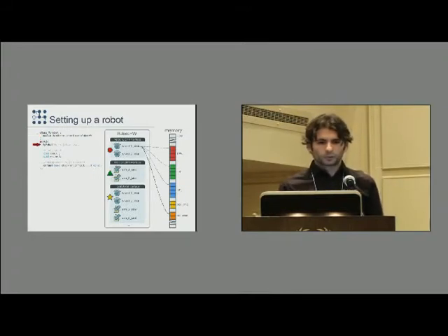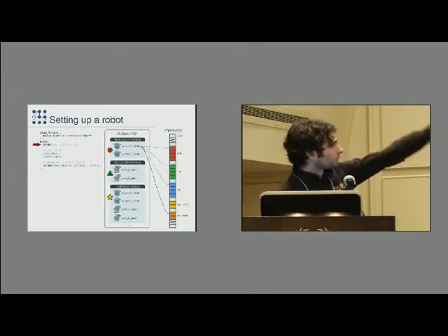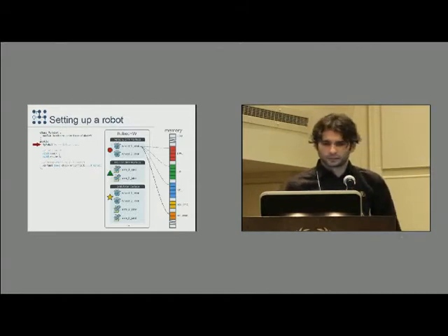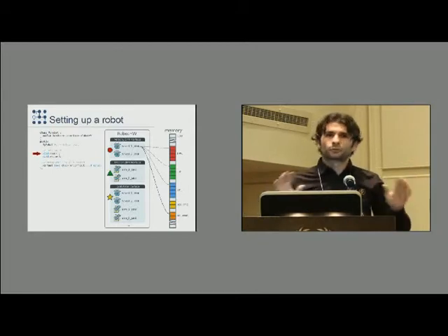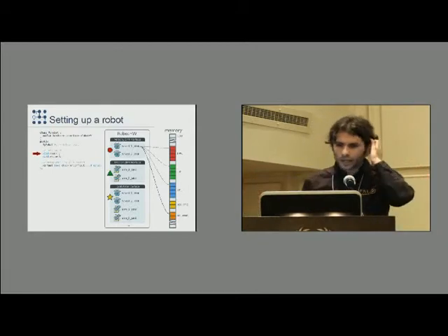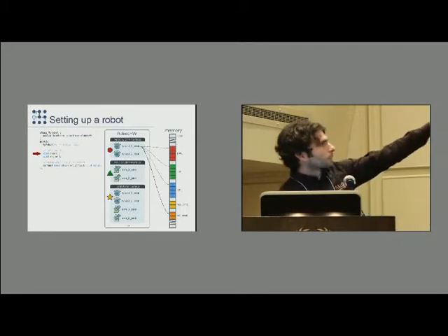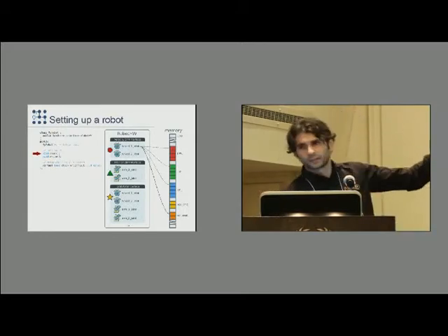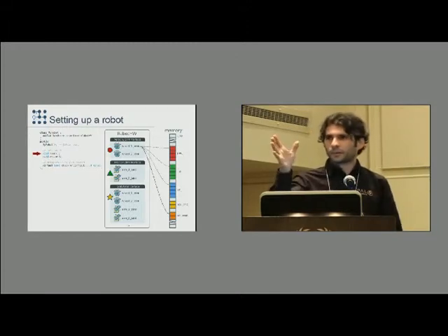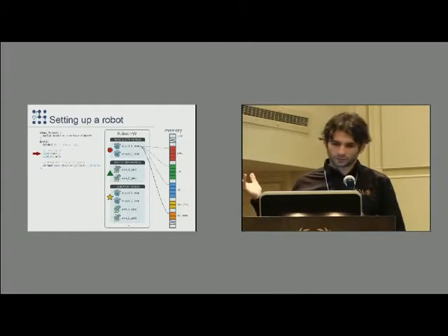In the constructor, you would set up your robot, which is basically filling up what you see in the drawing. And then there's a couple of methods where you read and write, and this is up to you. This is where ROS Control can no longer help you. When you read, this is where you would populate the raw data with your robot state, and when you write, this is when you take the raw commands and send them out via CAN bus, Ethernet, EtherCAT, serial port, whatever.